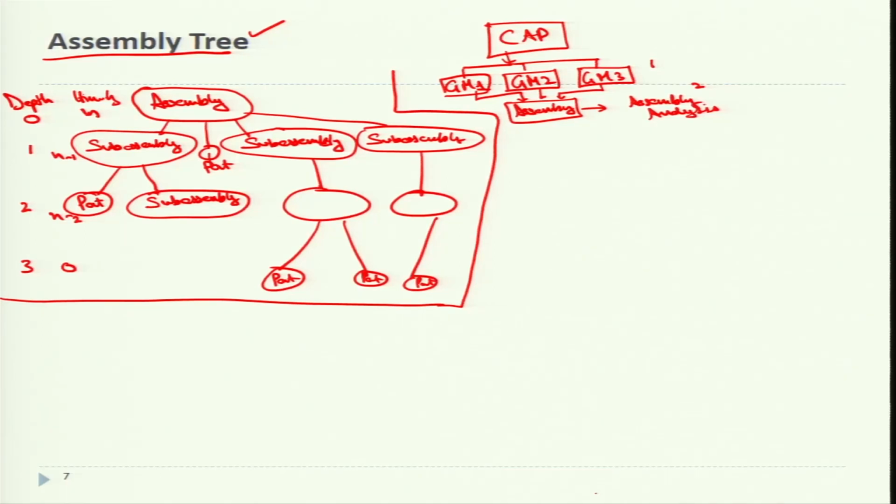So an important issue is not really creating the assembly but also updating it whenever required. Whenever there are changes in the design, or a change based on the feedback that we have taken from the customer, updates should be done automatically and correctly. That is why there are CAD models which are assembly based systems, and component based systems are also there. For example, Fusion 360 is assembly based software. SolidWorks is an example of component based software where each component can be varied separately. In assembly based software, if you vary one component, the whole assembly has to be altered individually sometimes.